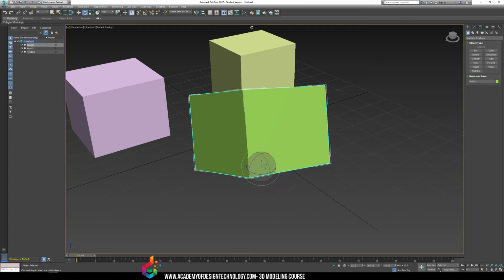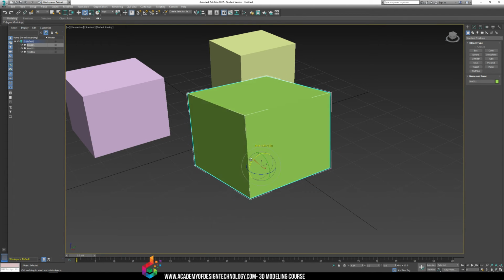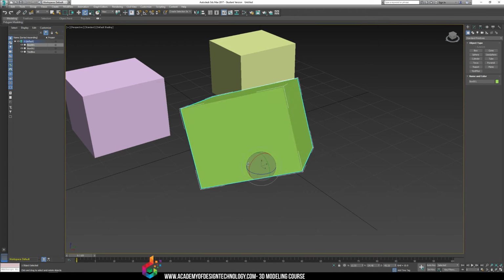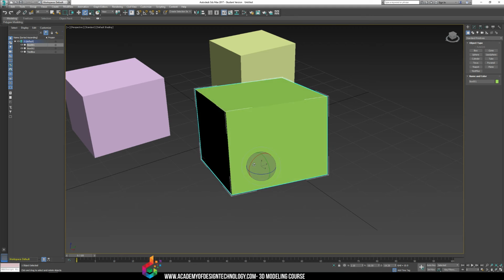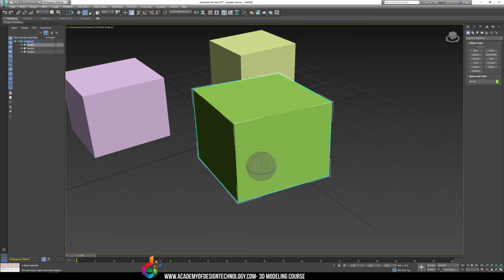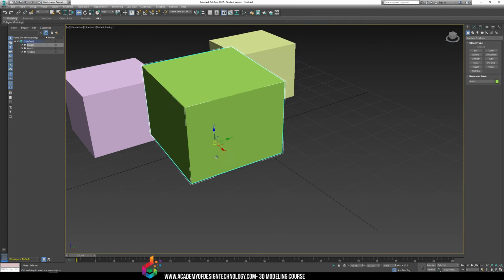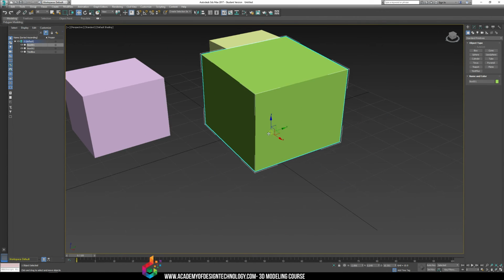This is good for getting precision if your object's a little bit more wonky than using normal dynamic measurements. So remember that left clicking anywhere in the orb other than the lines will go into freeform rotate mode. With W, we can move across any of these axes, or we can left click on this little box here and go into freeform move mode as well.